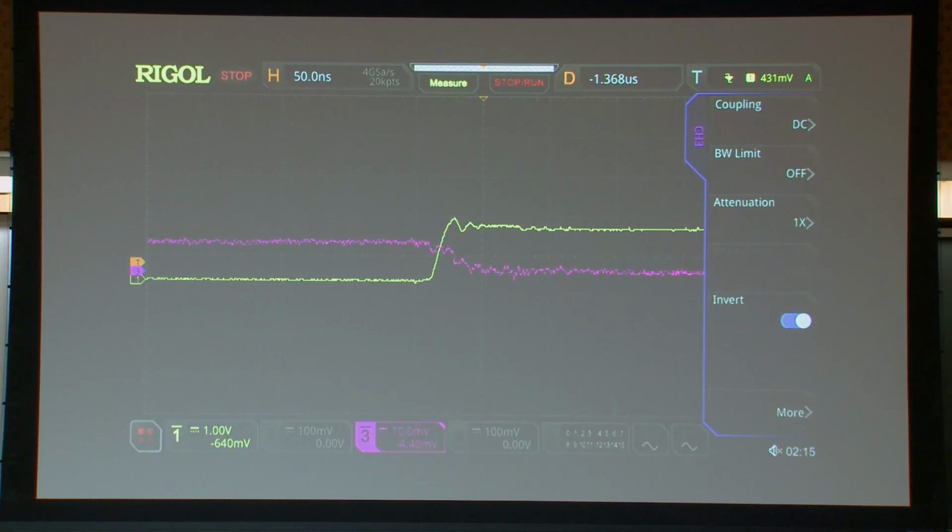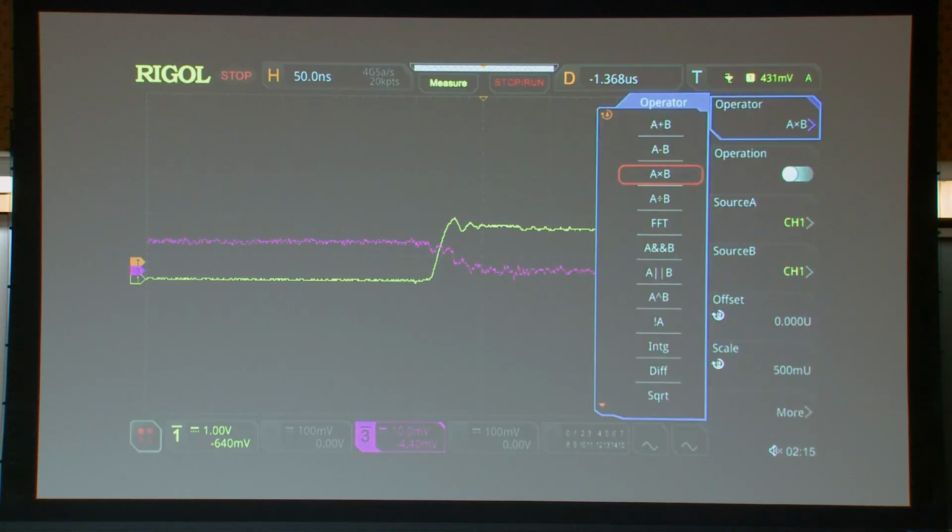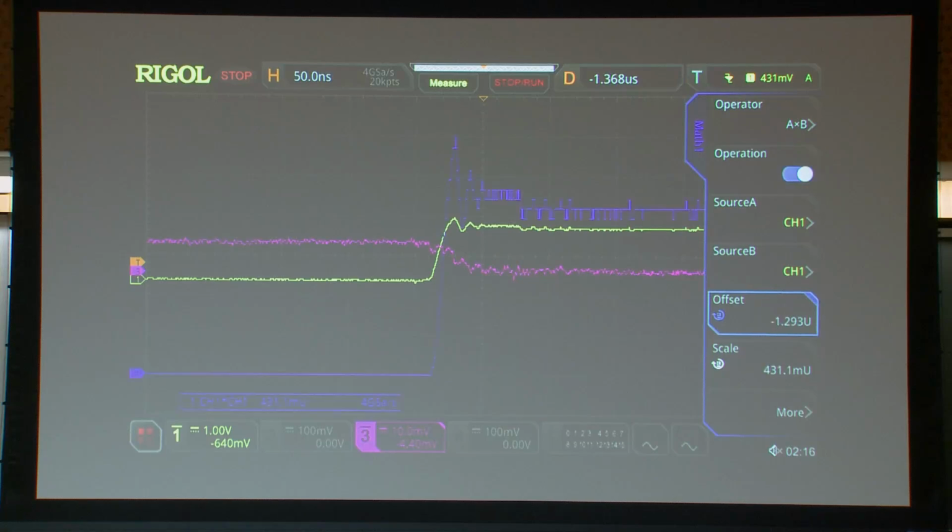So you can see the yellow curve is the current and the purple curve is the voltage. You can see that for hard switching, the voltage increases first and then the current decreases, which matches our theory. You can also observe that during its on state, the voltage has a very small value. That is the on-state voltage drop, which could be the RMS current times the RDS(on).